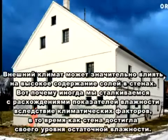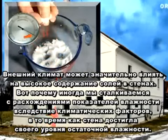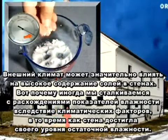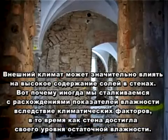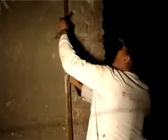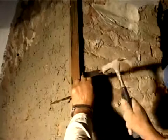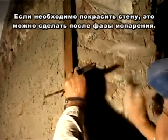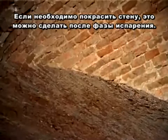The external climate might play a major role when walls contain a lot of salt. This is why we occasionally encounter moisture variations due to climatic factors, although the wall will have achieved its level of residual moisture. If the wall merely needs a new coat of paint, it should be painted after the evaporation phase.